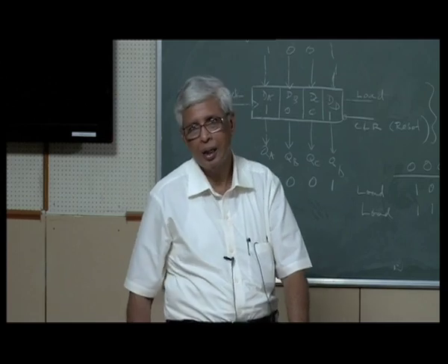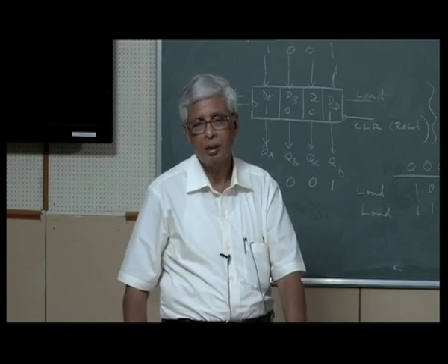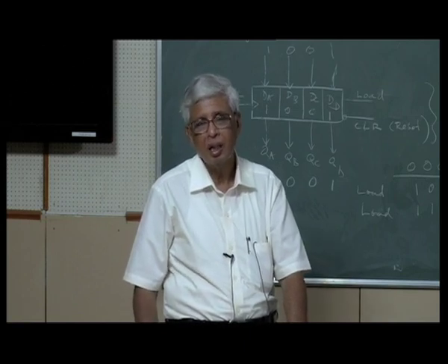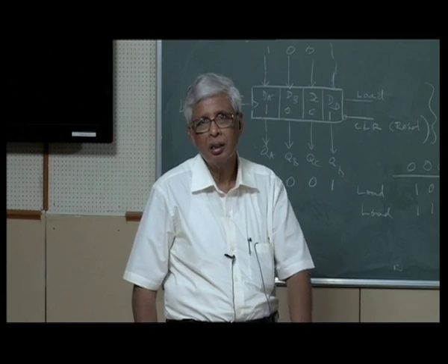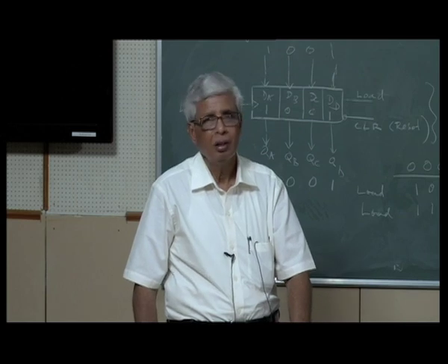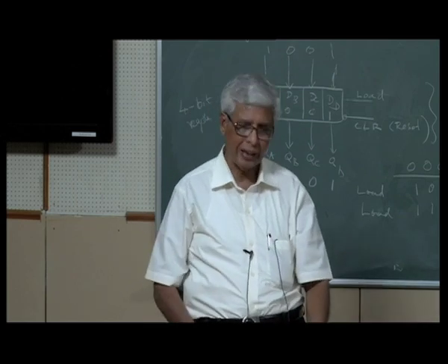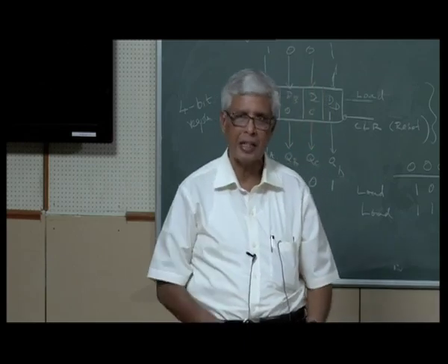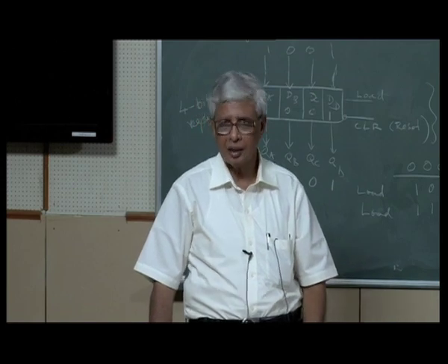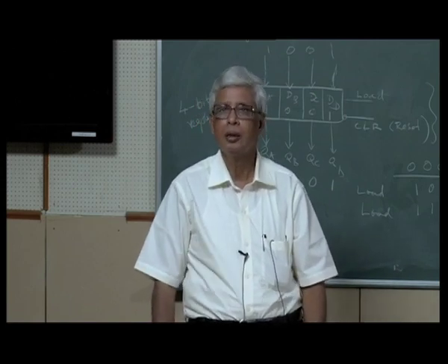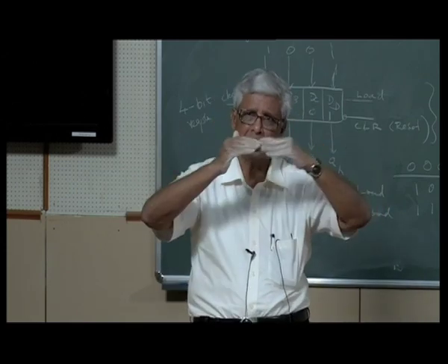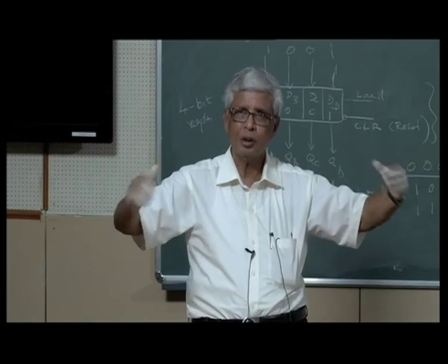has 2 power 10 addresses, which means 2 power 10 registers. They have a common clock, which means when the clock is high, I want to change only one register. If the clock is common, then the whole data will change. You have to address it. Address, register and the clock together will only change. You can't just arbitrarily change anything you like. Address has to be given. Once the address is given, only that location will change. So the same clock will work.